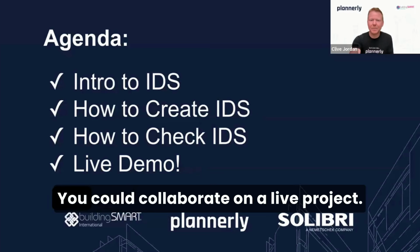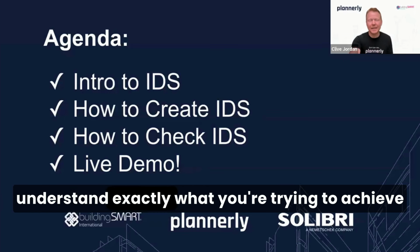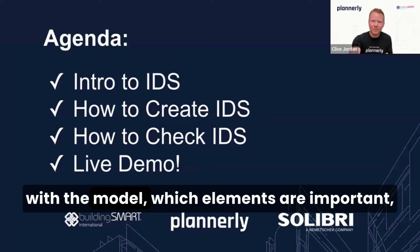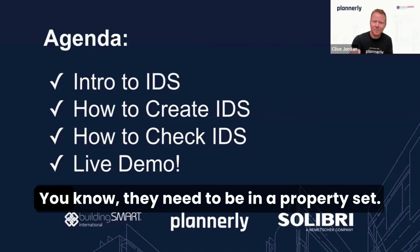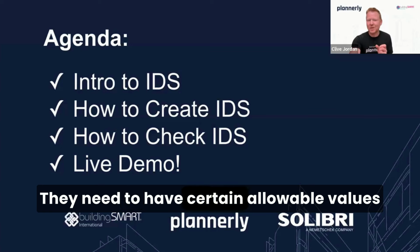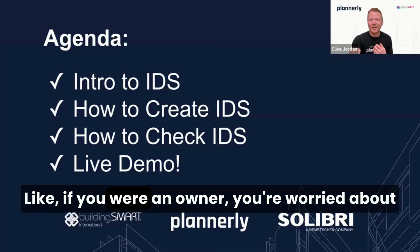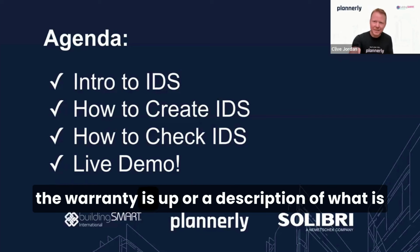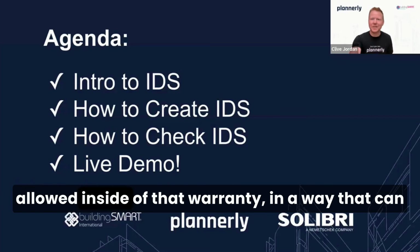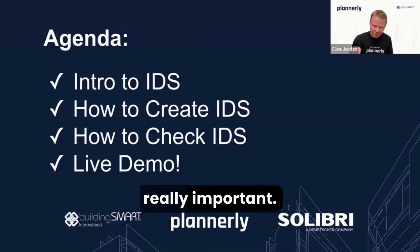You could share a link. You could collaborate on a live project. And inside of that workflow, you can really understand exactly what you're trying to achieve with the model, which elements are important, which properties are important. Are you worried about them? You know, they need to be in a property set. They need to have certain allowable values, or they need to be in a certain format, as a date or something. If you're an owner, you're worried about collecting warranty details. You need to have when the warranty is up, or a description of what is allowed inside of that warranty in a way that can be then read into your operations and maintenance tools. So being able to define that is really, really important.